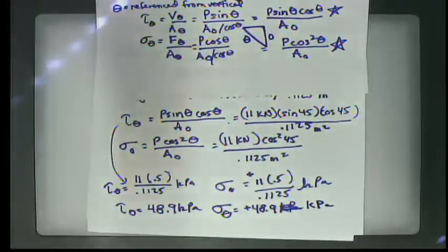So, this is a fundamental identity: at an angle of 45 degrees, when you have an axial load that's 45 degrees from an oblique surface, the shearing stress will have the same value as the normal stress. Okay. Also turns out that's the maximum value of shearing stress. Shearing stress is maximum when the force is... forget what I just said. I'm not even going to talk about that yet. So let's just say they're the same at 45 degrees, okay, which kind of makes sense.